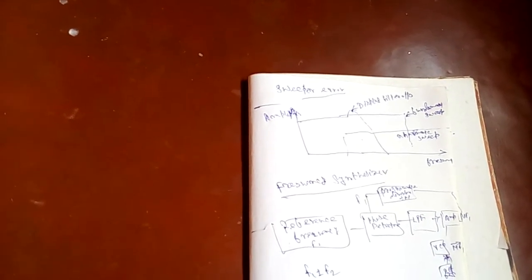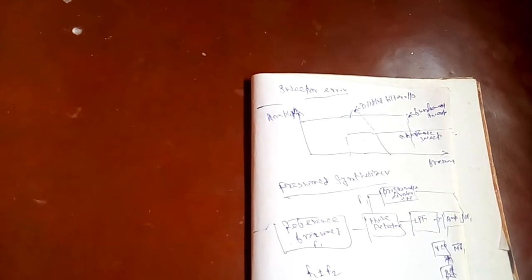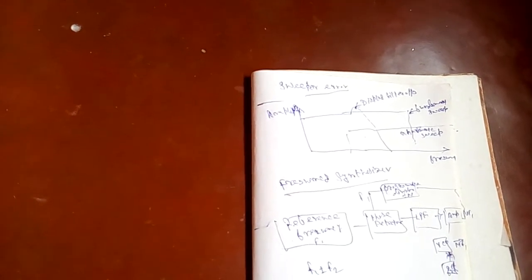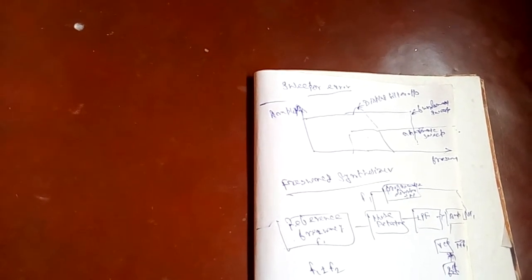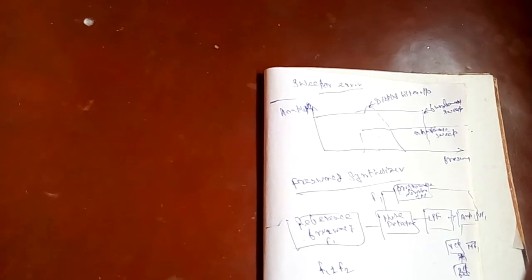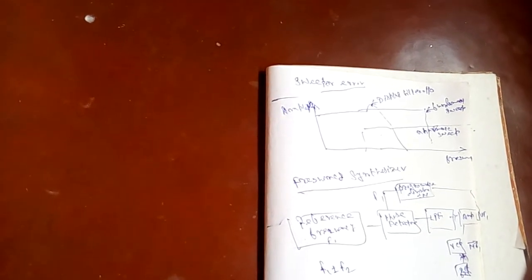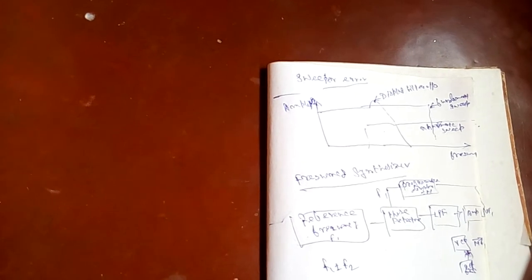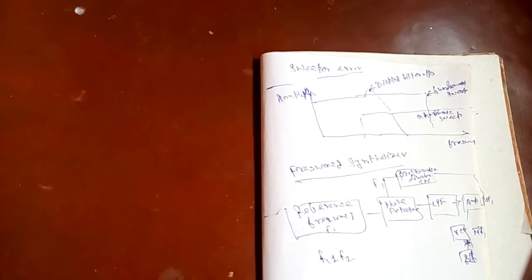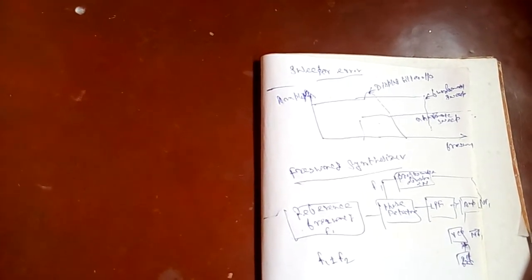Typically it is a few milliseconds or microseconds. So for the indirect frequency synthesizer, the problem is the frequency range. The VCO which covers a wide frequency range needs a large divider ratio in the programmable divider, and noise within the loop bandwidth increases.